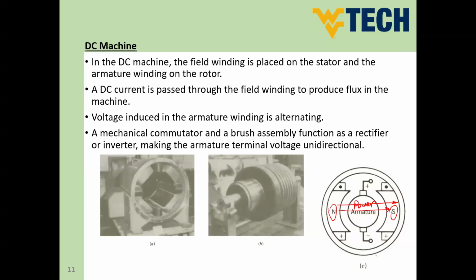The opposite action is when you supply the inner structure here with electricity, a current will flow in the windings, which will be on the top of the structure of our rotor. In this case, you will have a magnetic field and a current-carrying conductor. So this will apply a force on every conductor, causing the machine to rotate, making the motor action.